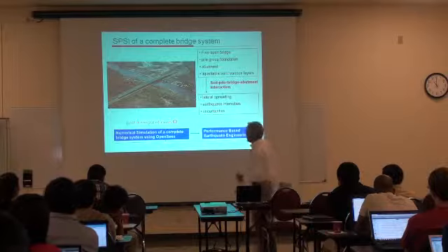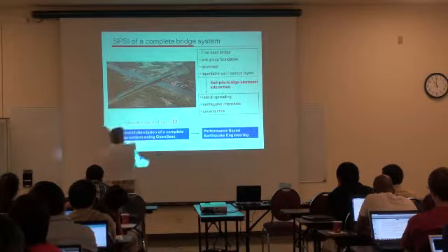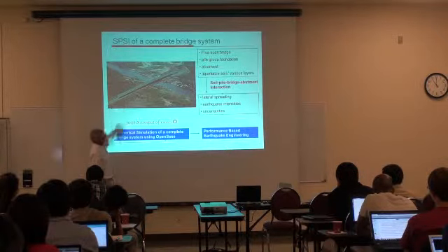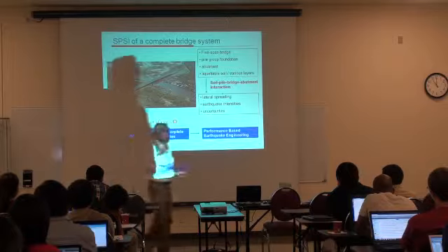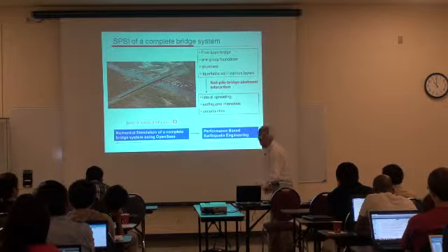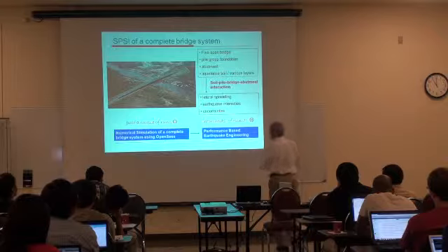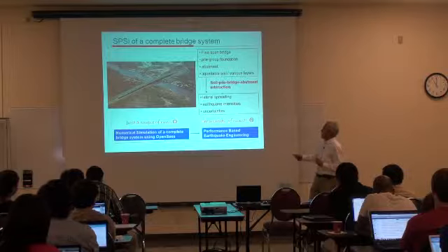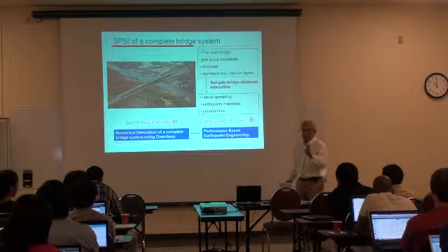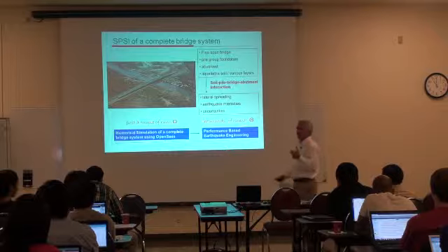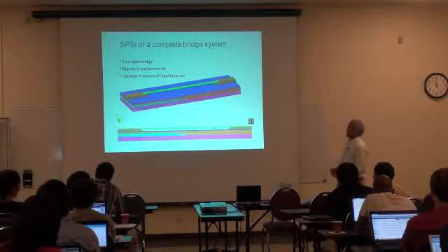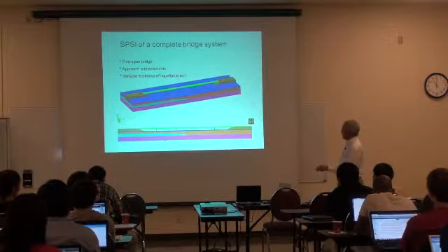So the thing is that if you want to do just one simulation, or a couple of simulations, I can put time on the model, developing an accurate three-dimensional model. But when you are doing performance-based analysis, you are talking about thousands of runs. And then my phase changes to this. Because if I have to do thousands of runs for different earthquakes, modeling the whole thing, I can be here for years. So again, this is the type of schematic of what we wanted to model. This is a two-dimensional view of the problem, and we decided to go two-dimensional.